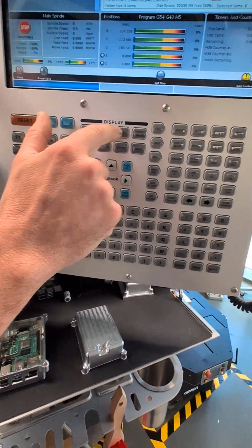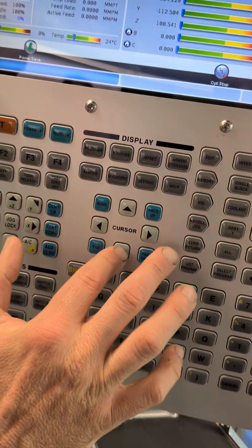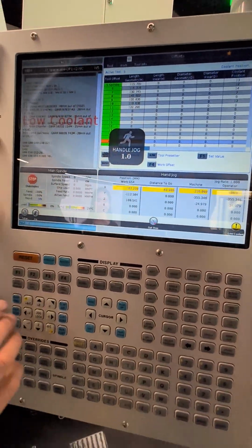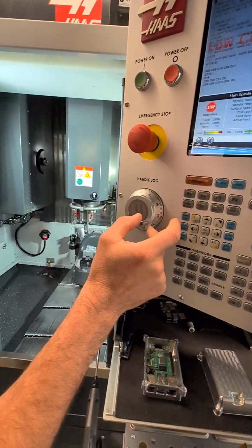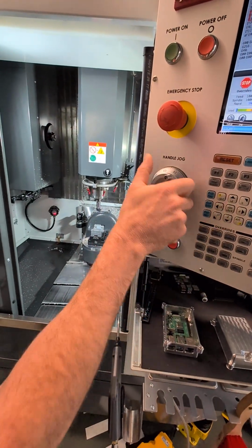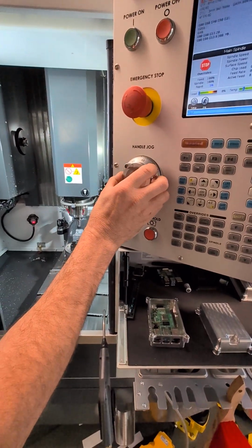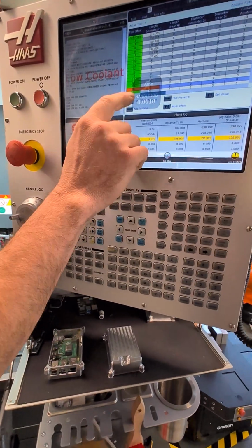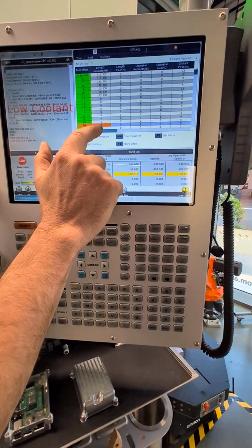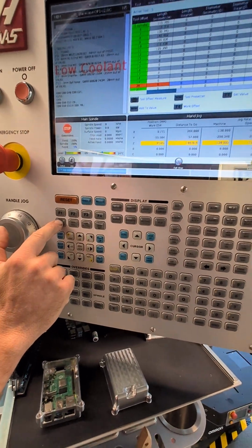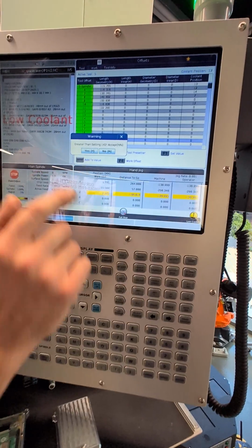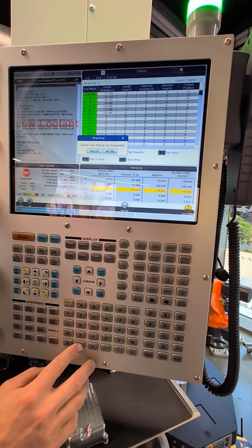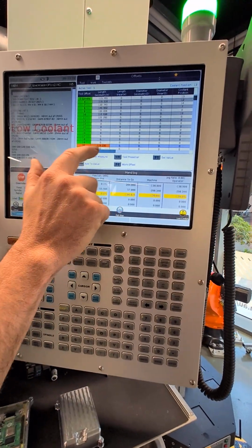Just for example, if we were to say it was tool 20, I've come down to the top of my job, or onto a tool presetter. Say that was the top of my job there. You found the top. You would go to your offsets page under the length geometry column and hit tool offset measure, and it'll say, is this greater than setting 142? That's just an offset change tolerance. You can change that, but you say yes, and it'll give you a value here.